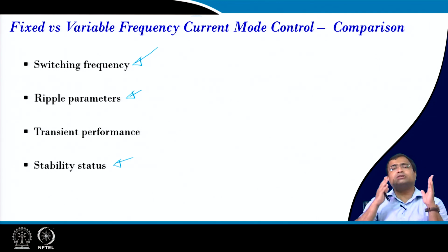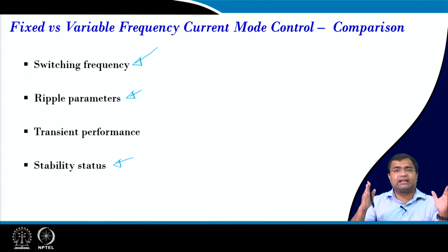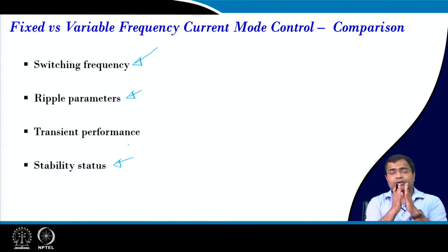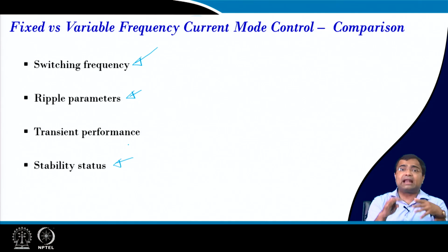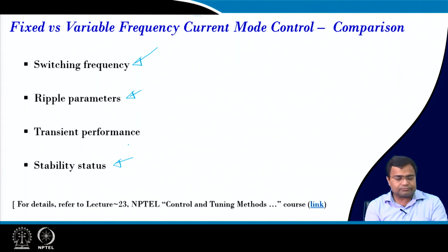So, constant on time is a very popular technique for low duty ratio operation, current mode control for high frequency, but constant on time suffers from frequency variation, which can be easily anticipated by means of digital control, and that is one of the objectives.